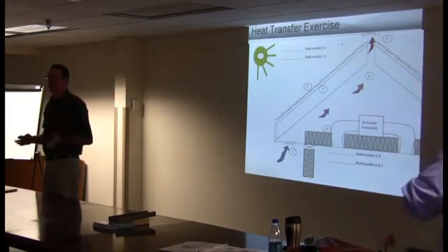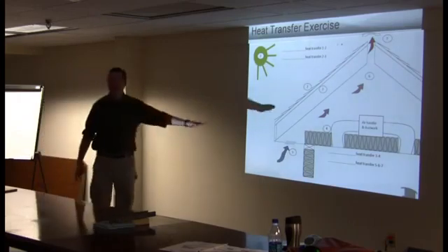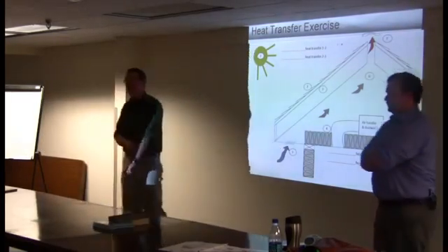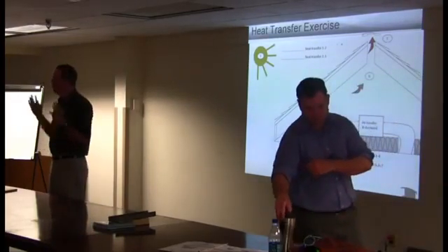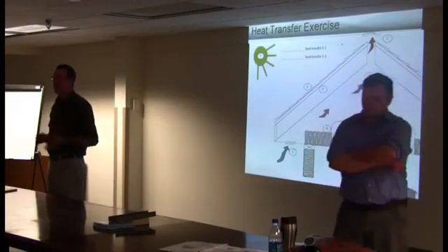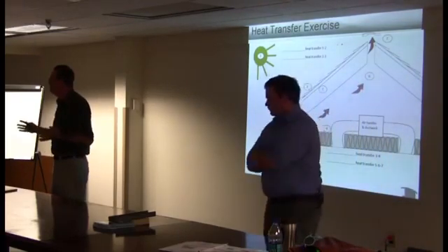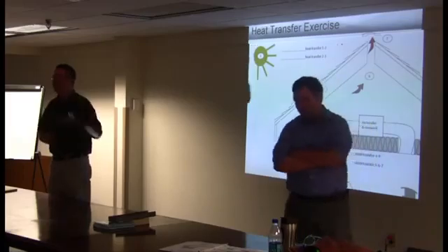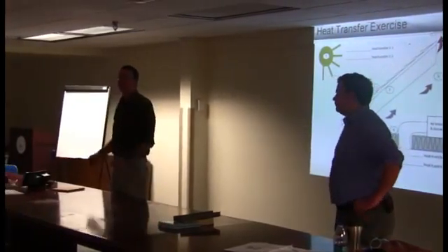That really, venting in a commercial building on a roof, unless it just really looks like a house like this, I would typically say you're much better off trying to put your insulation and make it continuous. And it seems like more times than not, I've seen commercial buildings where someone thought they needed to vent it, and they stuck vents in a soffit, and that was all they did. And basically, they just essentially let all kinds of moisture in.